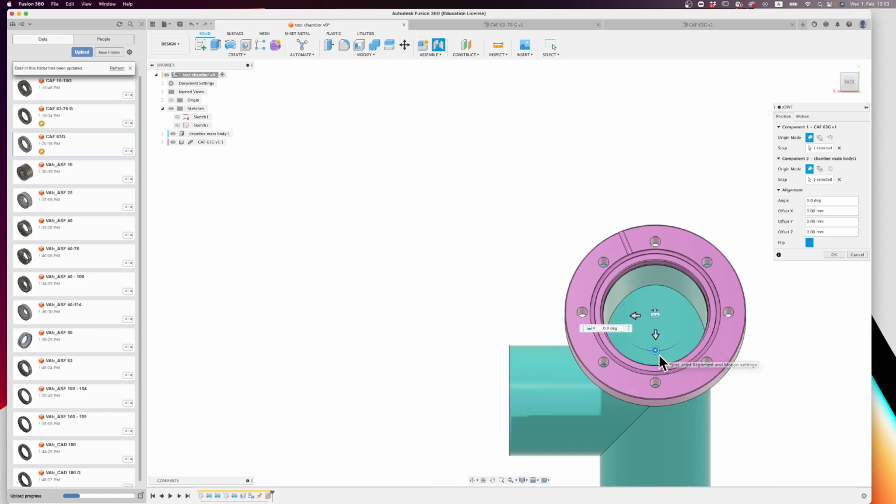So the last thing we need to define is the hole orientation. Always make sure that the hole orientation is correct on all of your different flanges, because you're going to mount parts to it that are not rotatable, like a valve. And if your valve can't be mounted in that direction, which you can check later with the assembly, then that would be a pity. So you would have to rotate it.